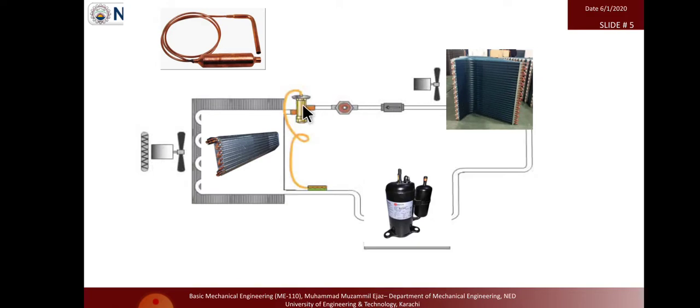Okay, and when this goes into the expansion valve or capillary tube, you see the diameter, the gas comes over here with some diameter, and then the diameter is squeezed down, then goes to the higher diameter volume of the evaporator. So from the low volume to high volume, the pressure will decrease, and due to the lower pressure, the temperature also decreases, and further it cools down. The air is passing from this point to this point, and when the air passes through the evaporator, the air will also get cooled down, and the refrigerant inside this tube,